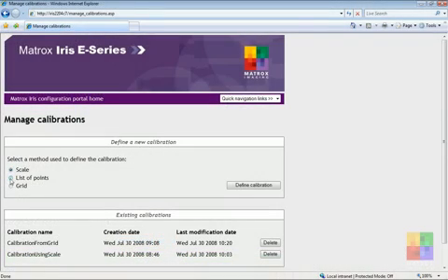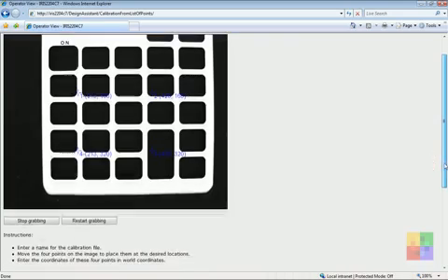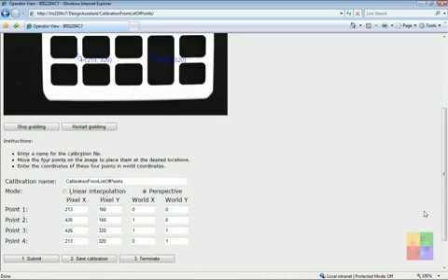The second calibration method is referred to as list of points. This method converts positions and measurements within a region from pixel to real-world units. It can also stretch the image and compensate it for perspective. We again follow the supplied instructions, starting with the name for the calibration.